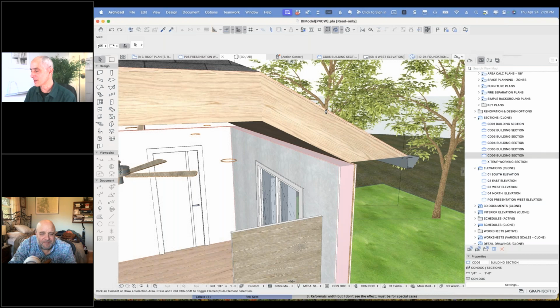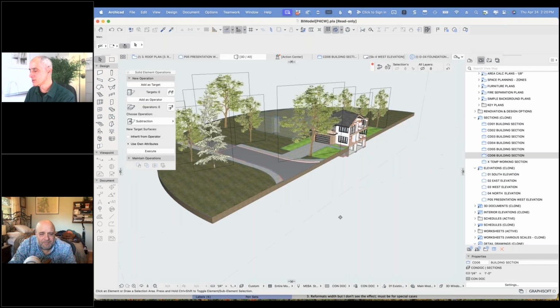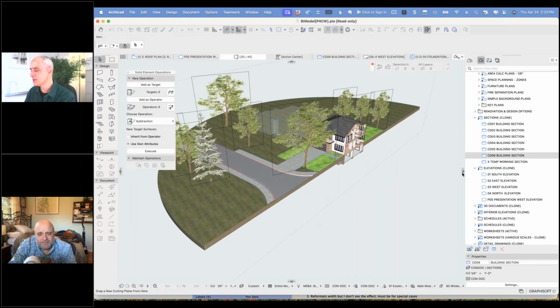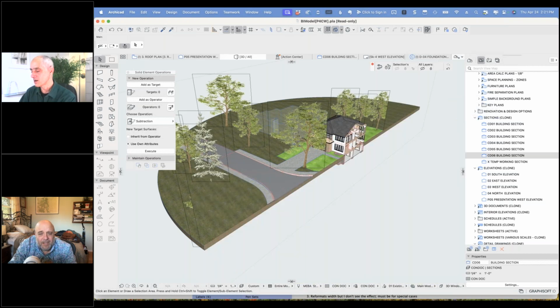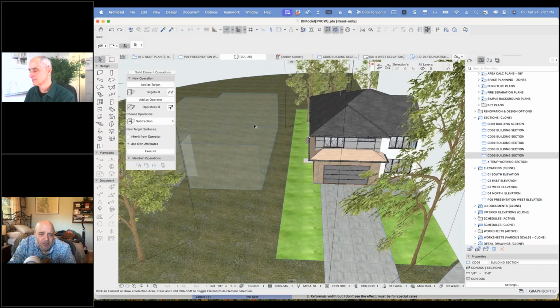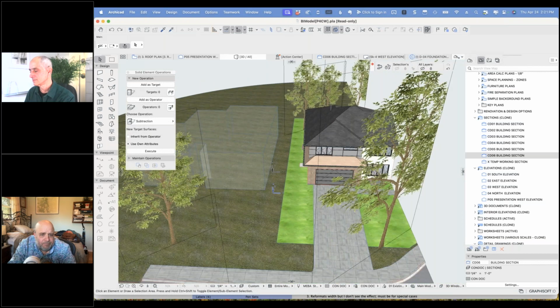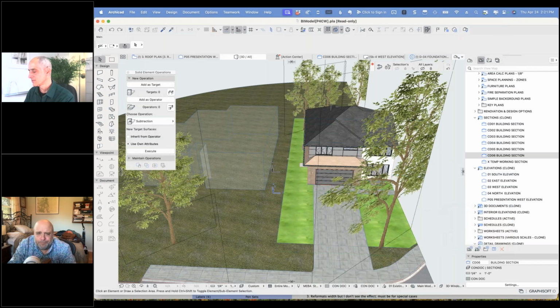Just take another quick look outside here. This is, as I had done before, a cutaway that's being done with the cutaway option here. You can turn that on or off by hitting Command Y. You can see how that view also shows the footprint of the adjacent houses. I usually model those in a thick slab glass, so I get some representation of context.